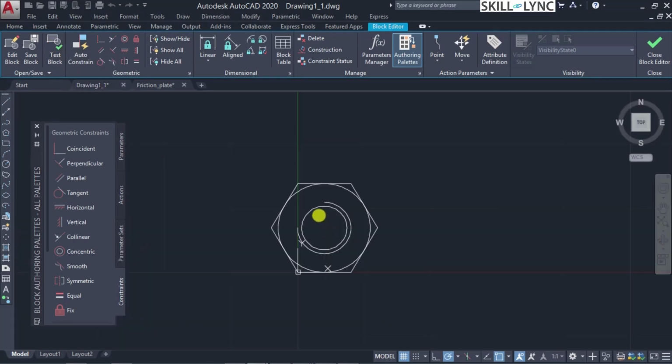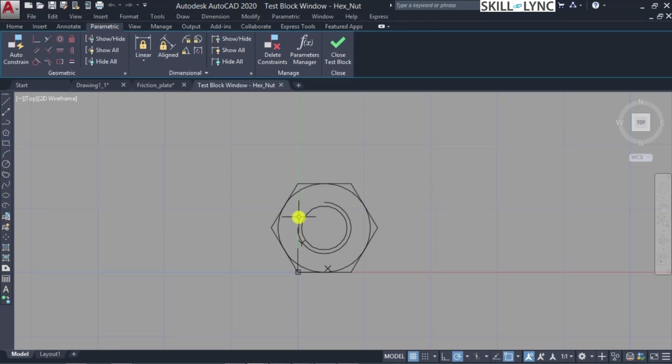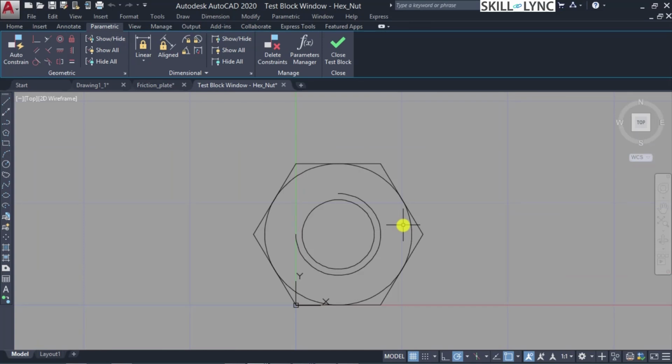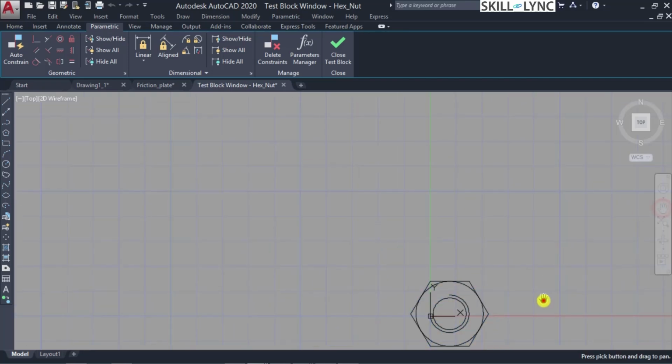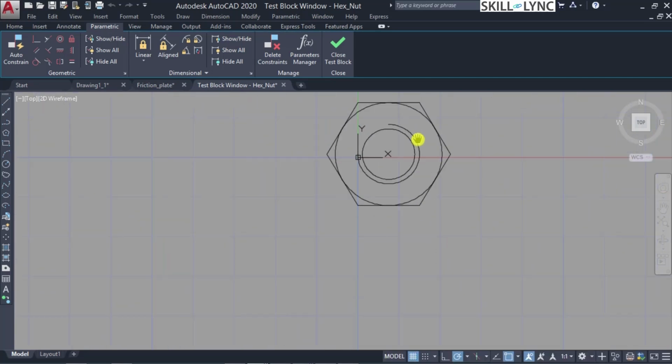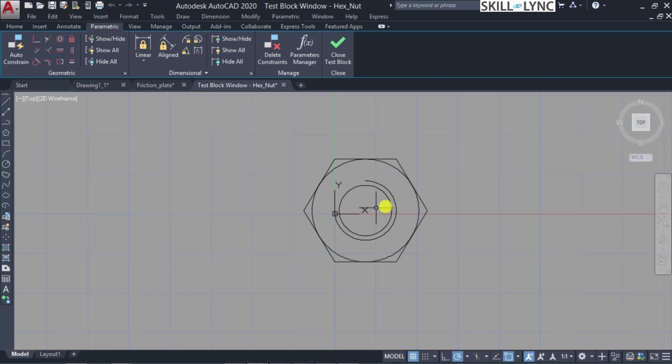When you go ahead and test the block, here we have the block reference. Now you can select the block, and once selected, you can see a down arrow button available here. This is your editing grip. Click on it, and you get the different options that you have. You can see that the base reference we created is highlighted with a tick mark on the left side, and if you want to modify it, you can see that the object gets modified accordingly, and our constraints are holding good so that the basic reference is retained. Likewise, we can optimize it.